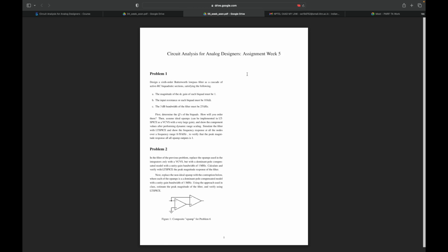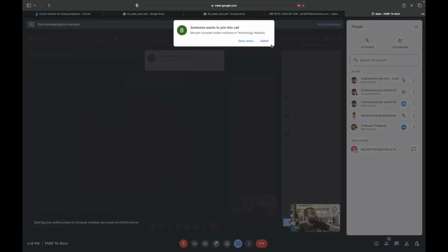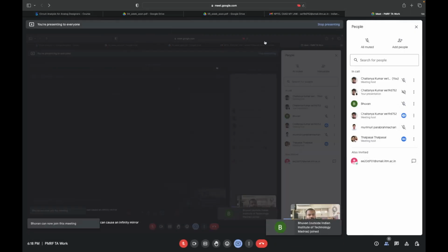No, sir. My doubt is, while you're designing, you mentioned a start frequency, and we have to start according to that frequency range, zero to... That's what I'm telling you. In dynamic range scaling, you have to check each of the nodes, and at each node you should have the maximum frequency response less than 0 dB.